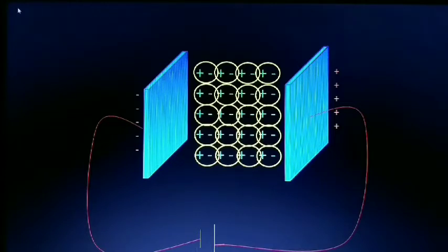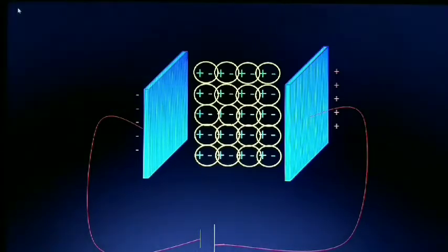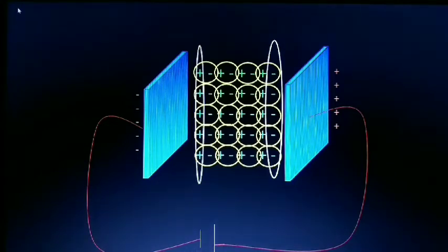So, in presence of the external electric field that has been applied between the two plates, the electrical polarization has happened. Now, the charges at the interior portion will cancel their effects, but at the surface of the dielectric material, the charges will remain unaffected because there are no opposite charges nearby in order to cancel their effects.